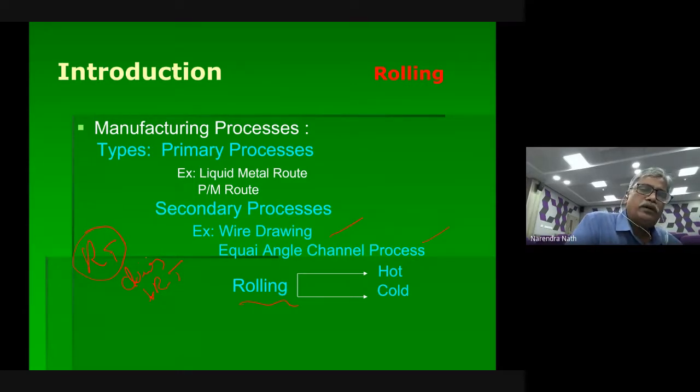When you go for a process with temperature, you can see changes happening with respect to crystal growth, or even further metallurgical changes. When we say hot, normally it is above the recrystallization temperature of that alloy. So that is the meaning. If I am using anything lesser than that, I can still call it cold only. Okay, with this, let us move on.